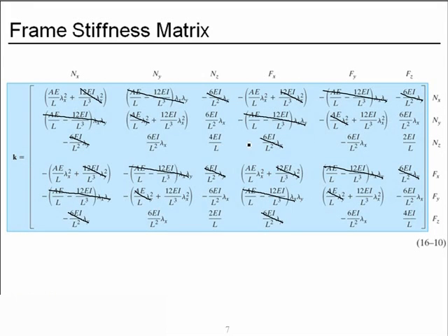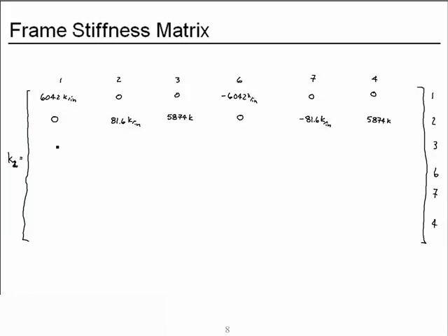And then we have 4 EI over L and 2 EI over L. So we have 0, a positive 58.74 kips, 56.3900 kip inches, 0, a minus 58.74 kips, and 2 EI over L, 28.1900 kip inches.